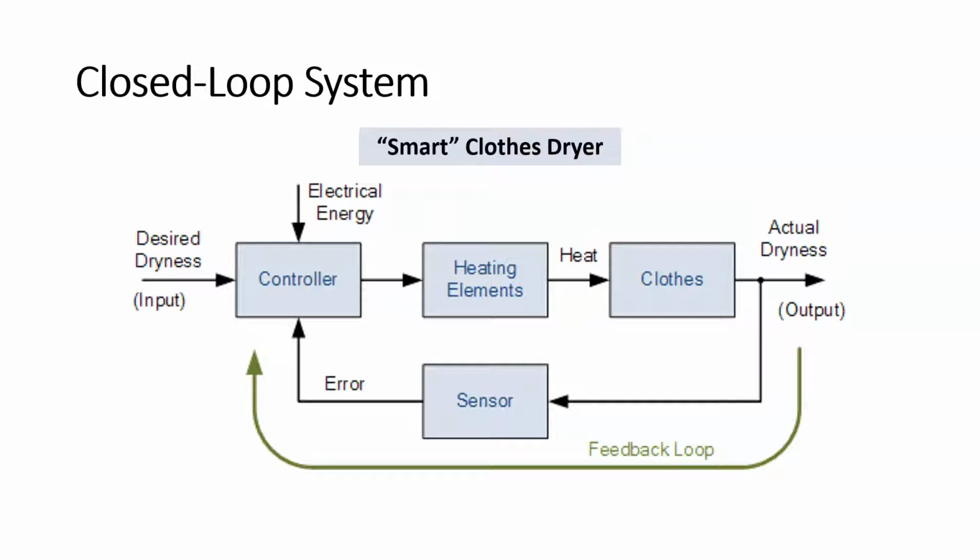There's safety mechanisms that are going to tell it if it's collided with something or if there's something in the way. There may be a vision system. So there's many, many sensors that are going to keep the robot moving until it gets to its desired point, or stop it if there's some interruption to that. All right, so that's why a robot is always a closed loop system, or especially industrial robots.